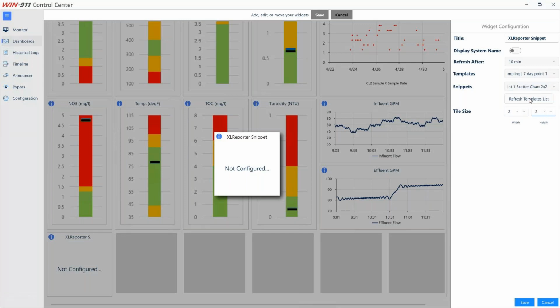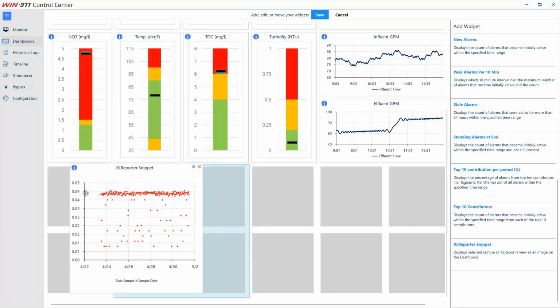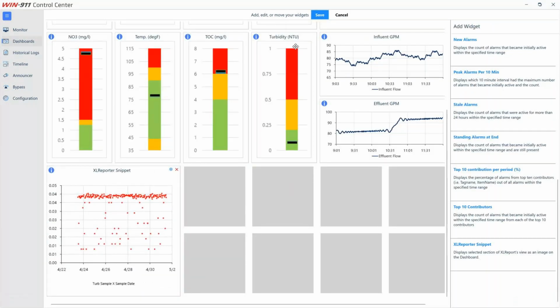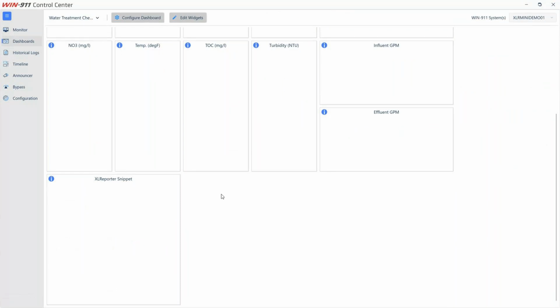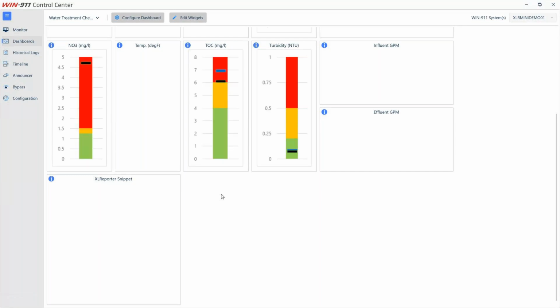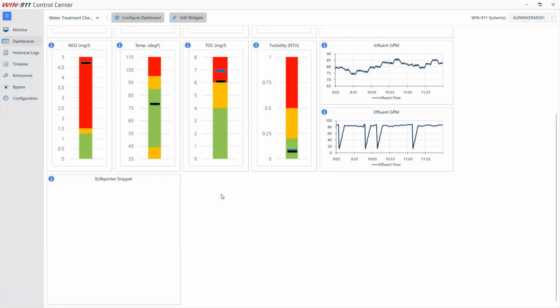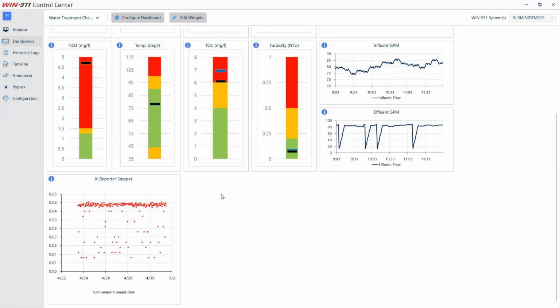And we want to make this widget take up a 2x2 size on the grid. And once we do this, this information will be on that dashboard. It'll refresh automatically in the background. So you can use this as sort of a lighter weight version of something like an HMI SCADA. Obviously, those who use HMI systems know that this display isn't quite an HMI, but it's an easy-to-use, lightweight tool that you can deploy around your plant.